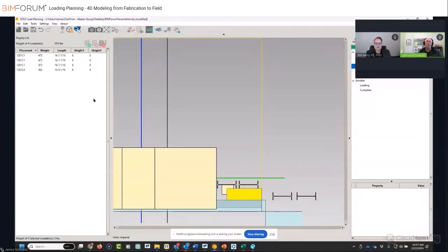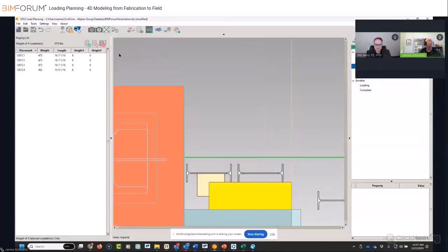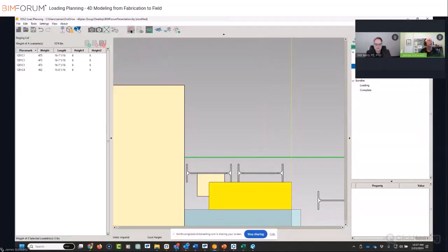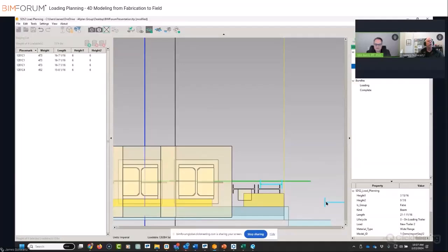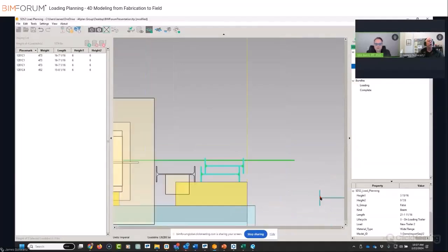And for general contractors running overall coordination, as you're planning your site layout, if you're working with fabricators that are utilizing technologies like this, one of the key things you're doing is understanding how much shakeout area you need to position steel on site, because you're not picking it from trailers.